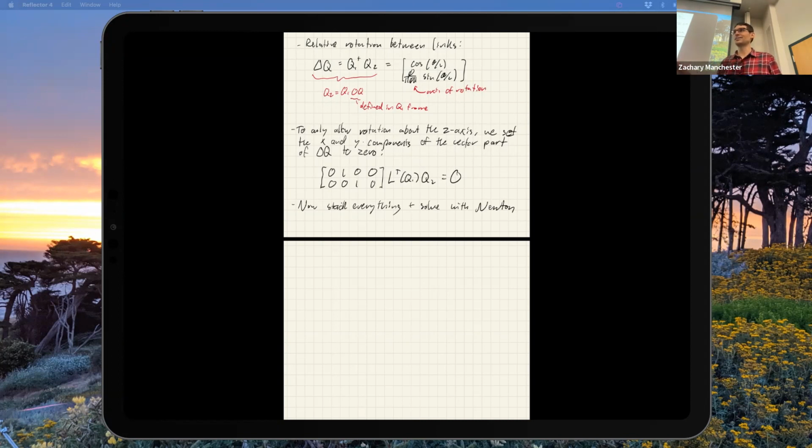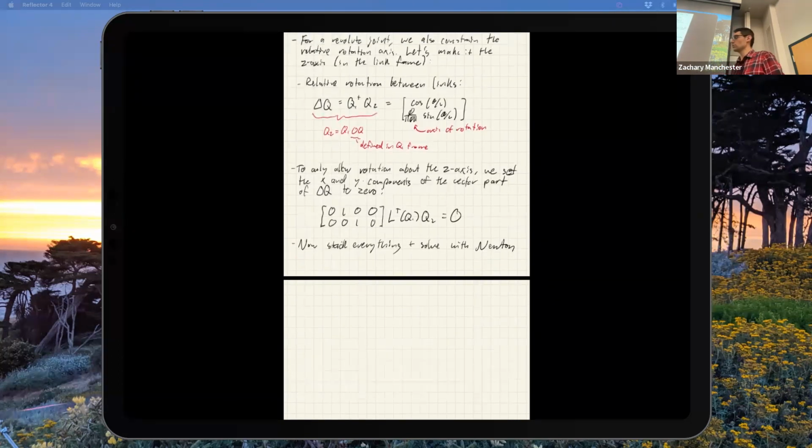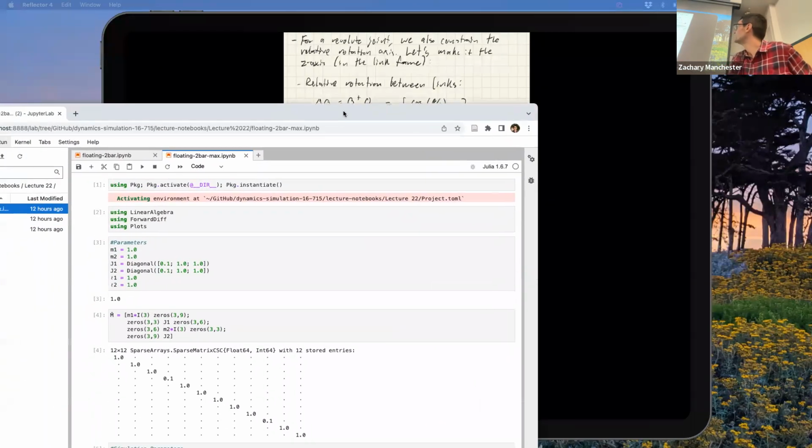Any questions about anything? The whole deal is you can write all this stuff in terms of quaternions. This is that C of Q. But I've got to play the quaternion tricks because I've got to solve that root finding problem in the quaternions and the position. So when I do Newton, as in the homework, I've got to differentiate this using the attitude Jacobian tricks inside the Newton solver, but modulo that, it's the thing you expect. Okay, cool. Let's see how to do it with some code.